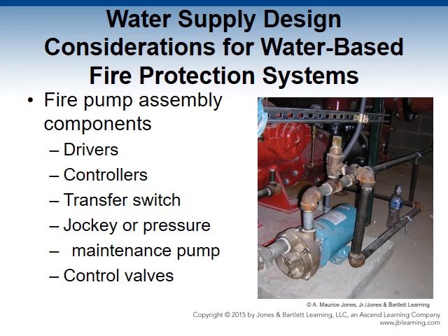Next, you have controllers. They are the brain for the fire pump system. They perform logic, sensing, and supervisory functions. They require certification for fire service duty. It must be installed in the room and as close to the pump and driver as is practical. They may start the fire pump electrically from a remote location or upon activation of a fire protection system.